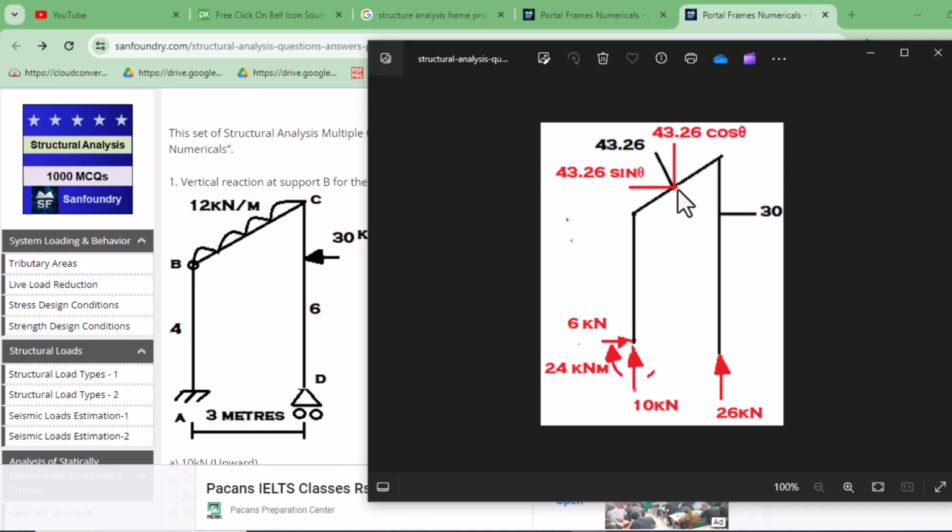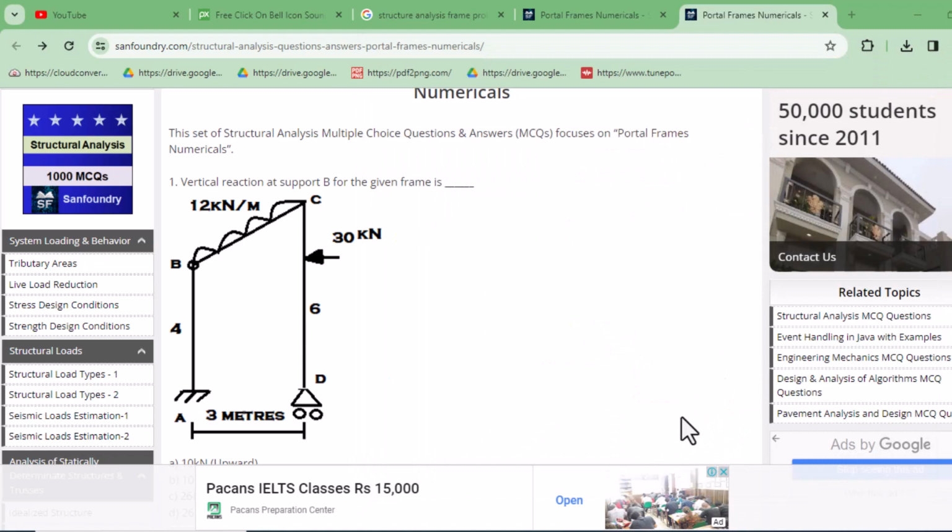Since we have to do the analysis of a building, we have many frames, we have many members which are inclined, and we have to apply inclined loads like wind loads. So it will take us much time in resolving these components and then applying again and again. So we will be using the local axis option here.